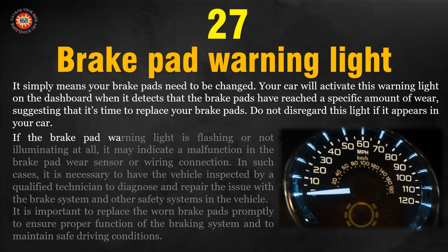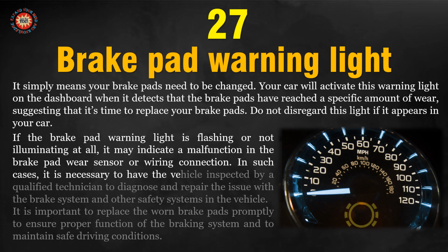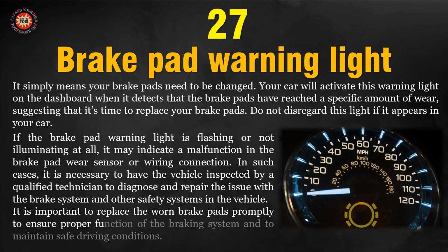If the brake pad warning light is flashing or not illuminating at all, it may indicate a malfunction in the brake pad wear sensor or wiring connection. In such cases, it is necessary to have the vehicle inspected by a qualified technician to diagnose and repair the issue with the brake system and other safety systems in the vehicle. It is important to replace the worn brake pads promptly to ensure proper function of the braking system and to maintain safe driving conditions.